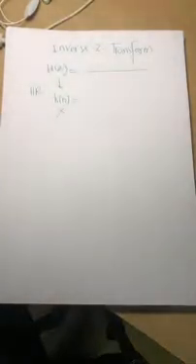And if you take an inverse, you get an h of n. h of n for an IIR system is an infinite impulse response. Neither can you store it in your computer, because you cannot store an infinite sequence in computer memory, nor can you use the convolution summation to implement a system. So that's why practically we have zero interest in finding the inverse Z transform.